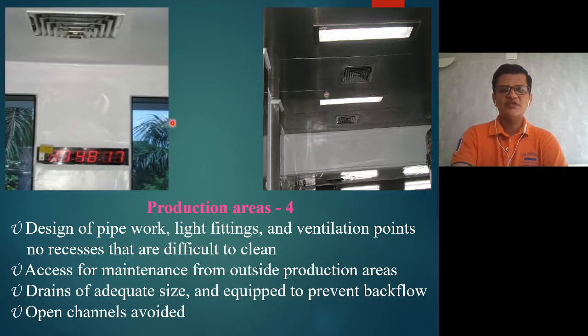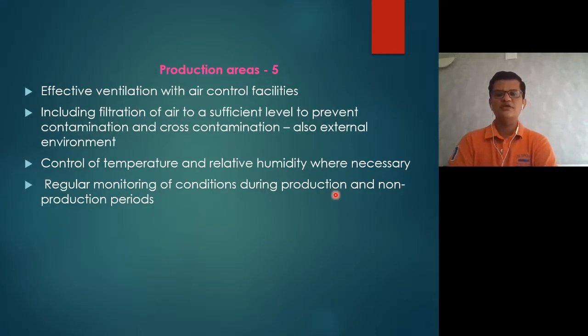You can see over there the design of pipe work, light fittings and ventilation points, with no recesses that are difficult to clean. You can clean each area. There should be access for maintenance from outside the production areas. The drains should be of adequate size and equipped to prevent backflow, and open channels should be avoided, so that insecticide can easily get into it.